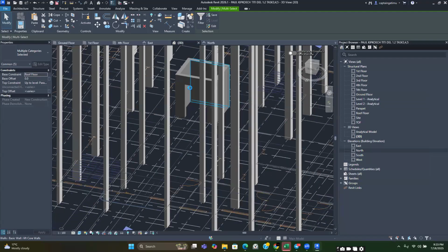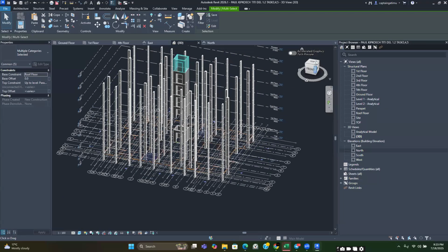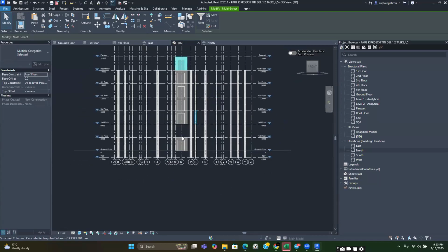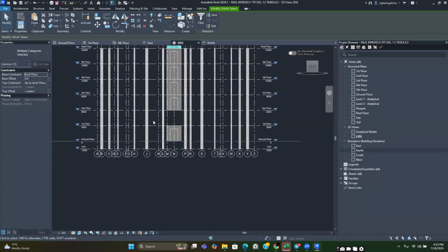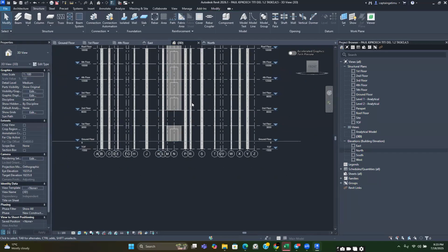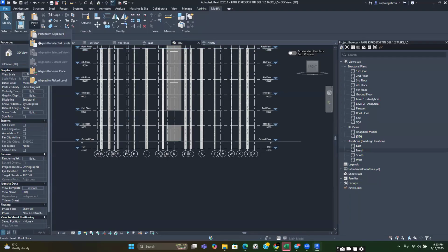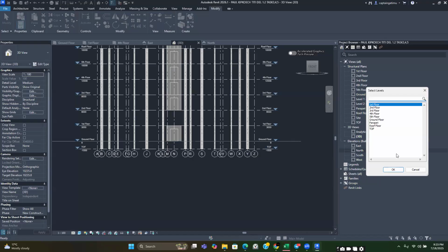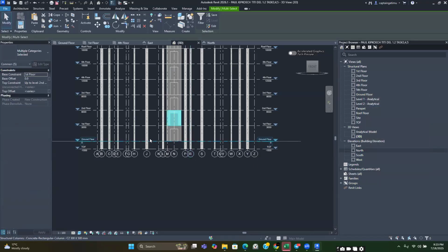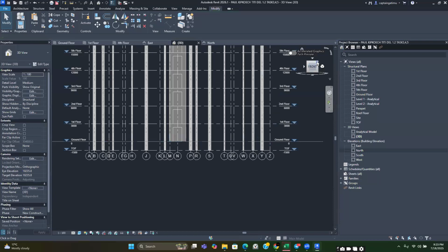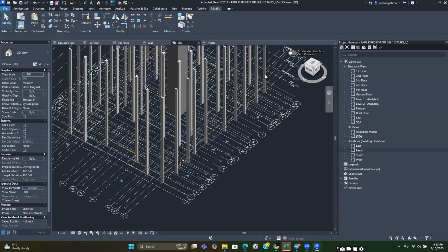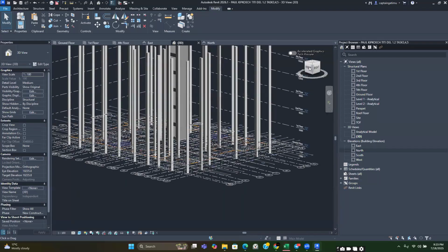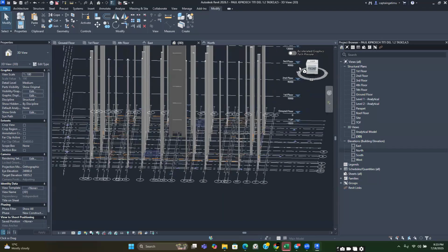And once you go to your 3D view, okay, so that did not go according to plan. So for this one, you have to copy them to the first floor as well. So if yours appears as mine, just go to modify, then go to paste, align to selected levels, and select first floor and copy your wall there. So you have your wall modeled there and you are good to go. Okay, you can see how easy that has been.